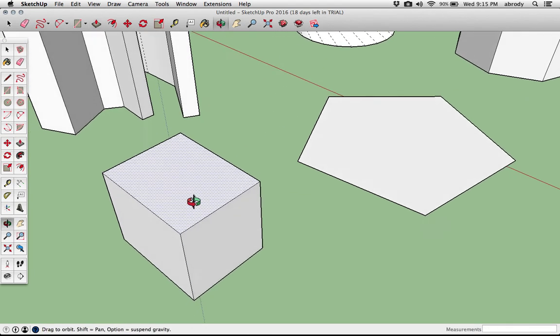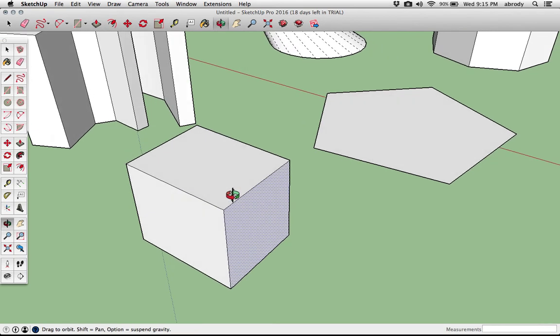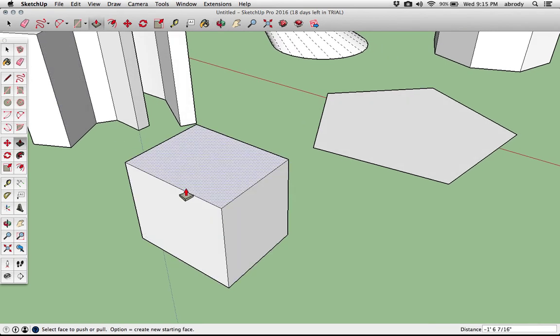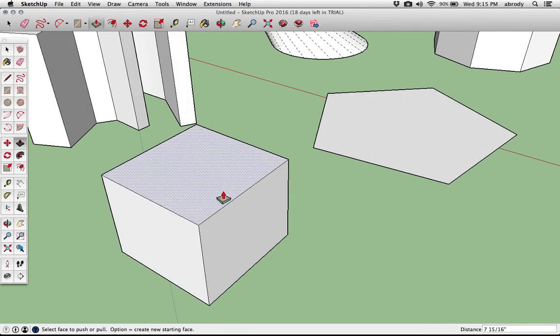Now, what if I wanted to create a really simple table? Well, we typically will model things using kind of base shapes, kind of like when we drew perspectives. Now in this case, if I just want to create a block with a blocky top on it, I can draw a rectangle on the side of this, and again I'm just kind of eyeing things, and I can use my Follow Me command. Remember the Follow Me command? One of our favorite commands.